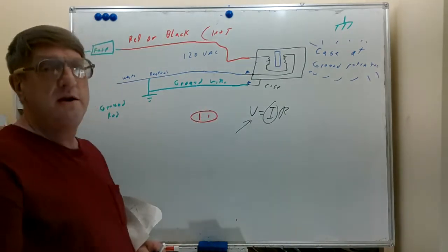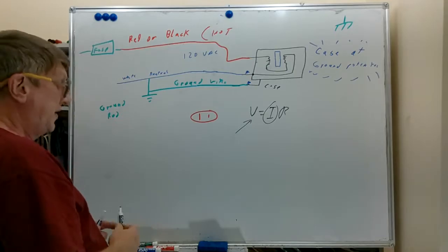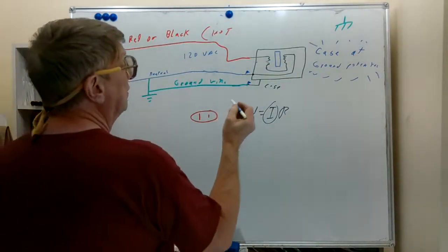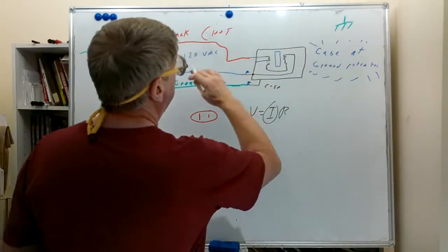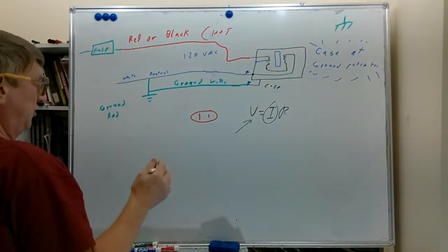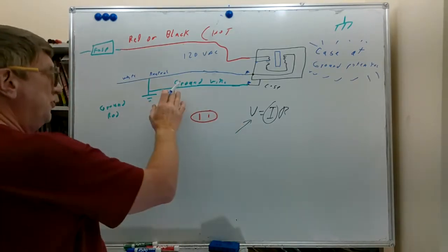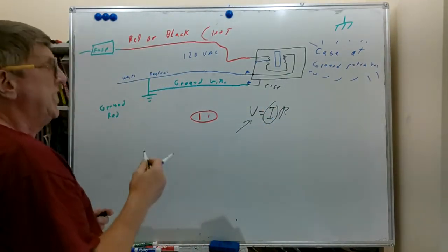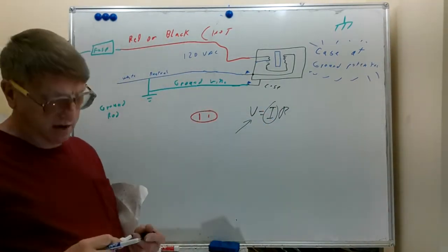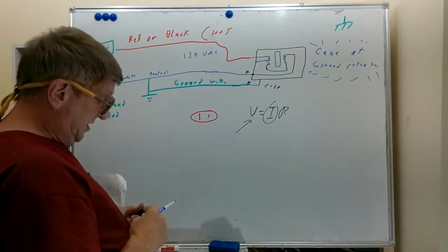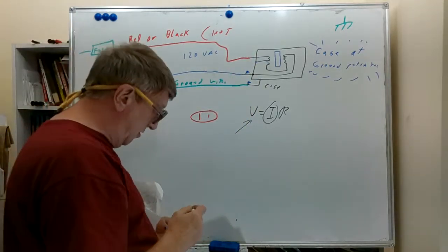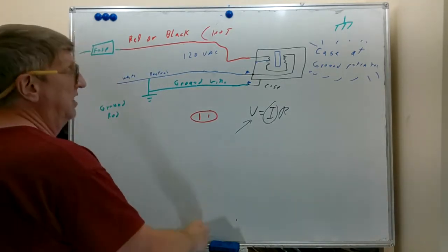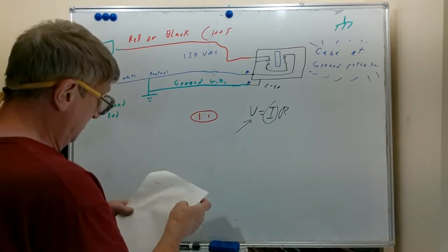The ground wire only carries what we call fault current. And when this thing broke and sagged over to the case, as we said, now we have some fault current, and we could have the IR drop in the ground wire, we could have something other than ground potential. But by not using this wire for anything other than a safety ground to keep the case at ground potential, we greatly minimize our chance of having the case being other than ground potential.